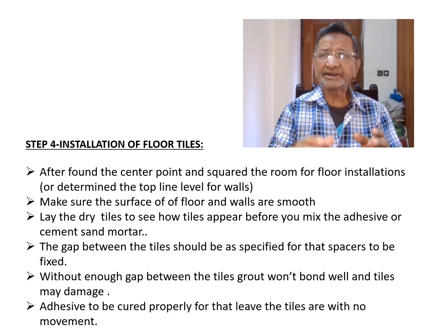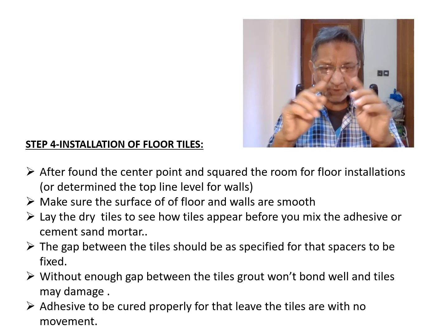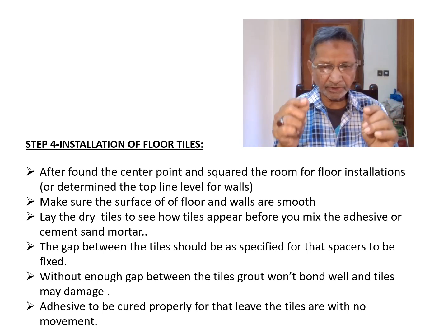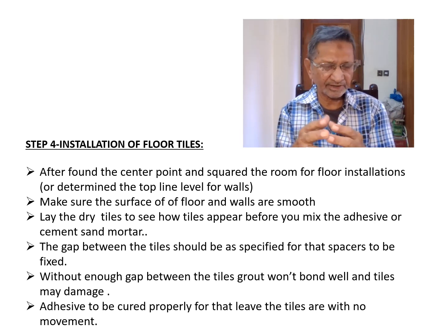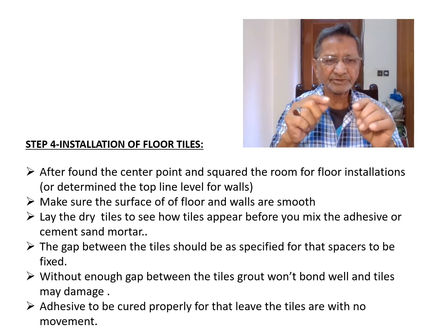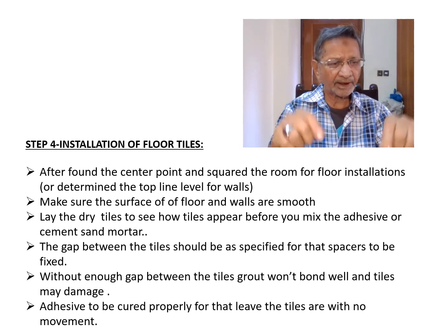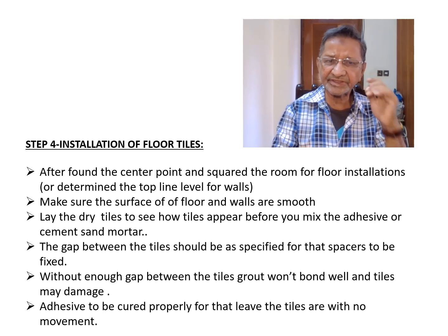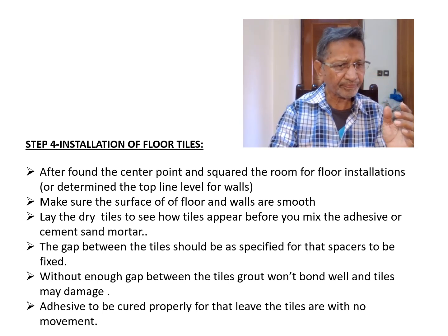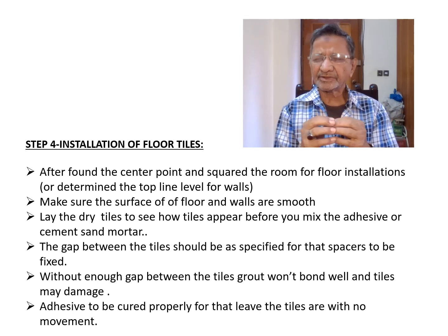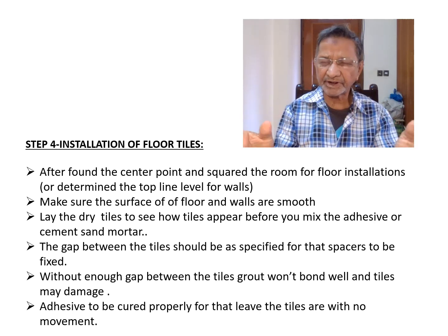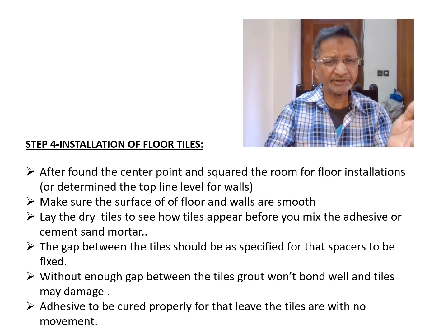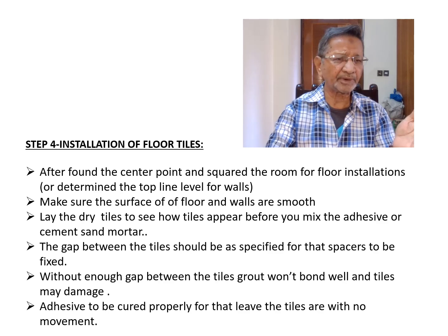Now, you have to maintain the joints. I mean, all the tile joints should be 2 millimeters as per I suggest, and these joints are to be fixed with the plastic spacers which are available in the market, so that you can get consistency in joints. Then allow the adhesive to cure and to dry. Then you have to do the next stage of work, which is in slide number 5.